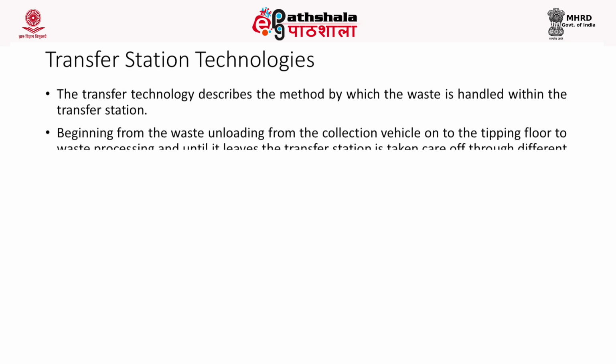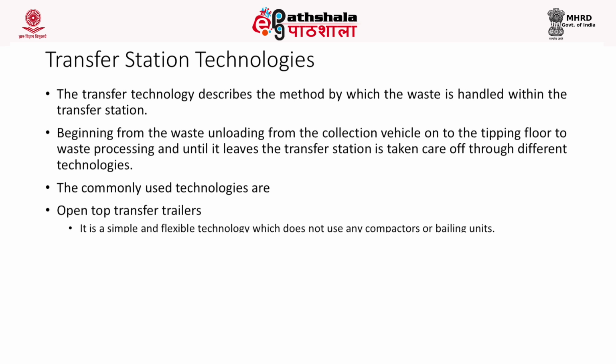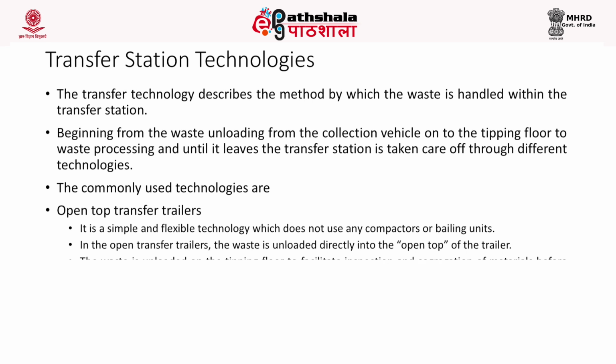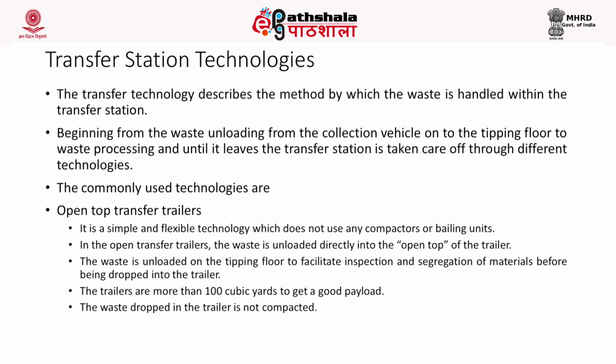So beginning from the waste unloading from the collection vehicle on to the tipping floor, to waste processing, and until it leaves the transfer station, everything is taken care of in these different technologies. The commonly used technologies are open top transfer trailer, surge pit, stationary compactors, pre-compactor system, balers and intermodal container system. Now first let us discuss the open top transfer trailers.